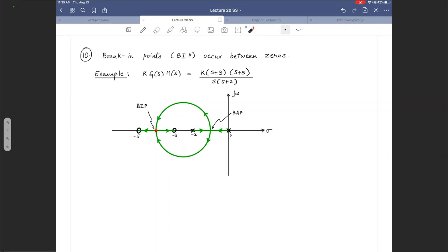Eventually it goes back to being critically damped, then overdamped, and eventually ends at zeros, right? So the system is moving through a lot of damping criteria over here. It starts off marginally stable, becomes stable but overdamped, critically damped, underdamped, critically damped here, overdamped here, right? So it's moving through many stages as you increase k.